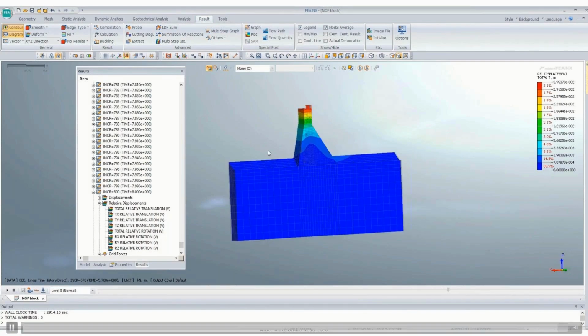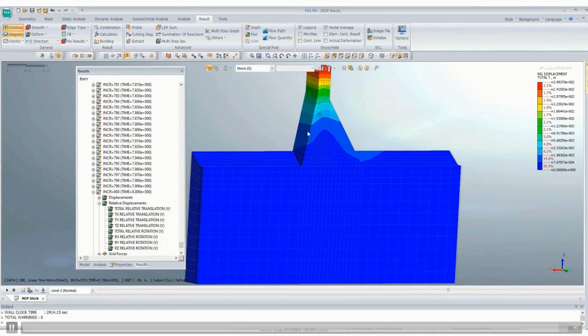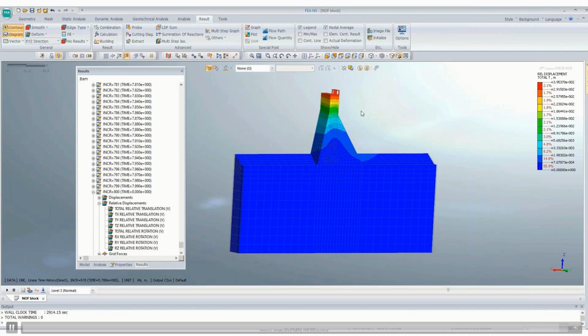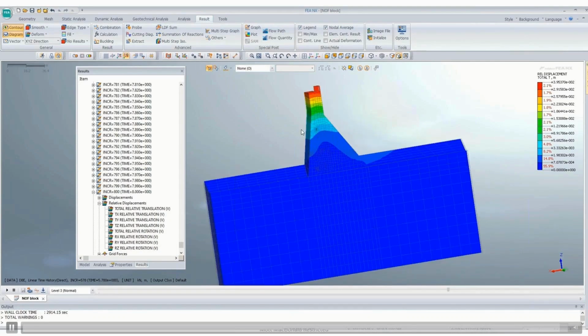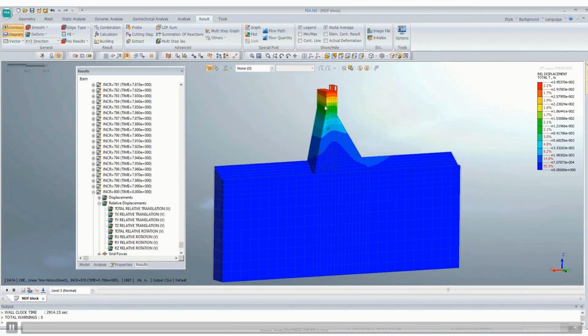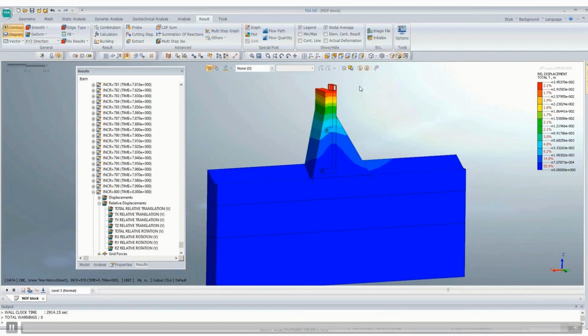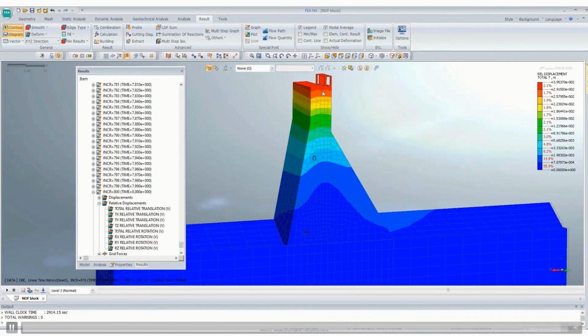In the next session, we will optimize this dam. We will put some more weight on this side so that it is safe in time history analysis for factor of sliding also, and then we will perform the stress analysis. We will see the DCR ratios for certain nodes on the upstream side. I mean, it should be more here because these are all flexural members. So we need reinforcement in these nodes.